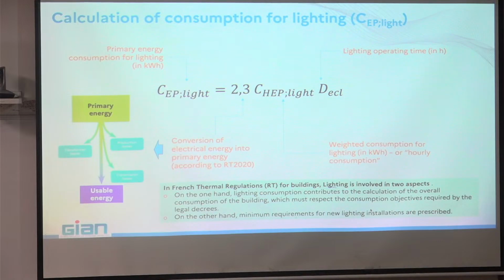Of course, we are engineers, electrical engineers. If I tell you how to use the energy, I show you the very simple equation: power, installed power. I count how many lamps I have. What is the input power? I add the parasitics, what the driver can use, what the sensors can use, plus, of course, multiply by the time, okay?